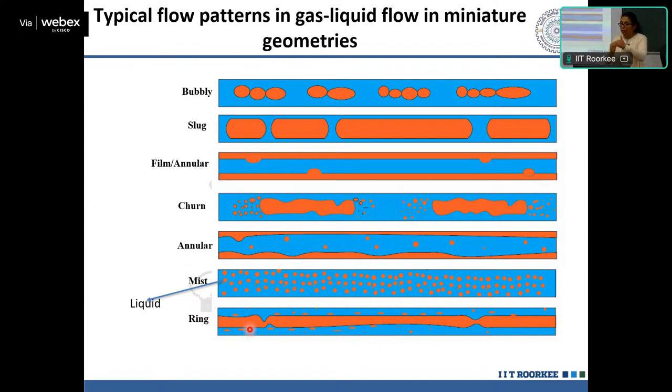From both sides there is accumulation, so it forms a ring structure on the gas core. It is compressing the gas core at certain points. So that is a liquid ring formation. It is different from the annular structure. They may be similar to a certain extent, but the distance in the annular is different from the ring.